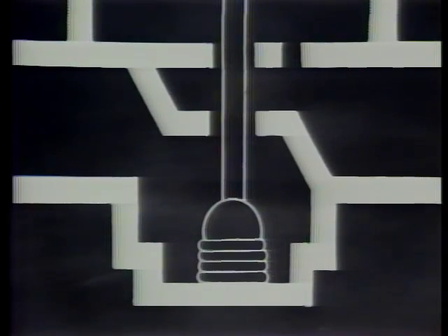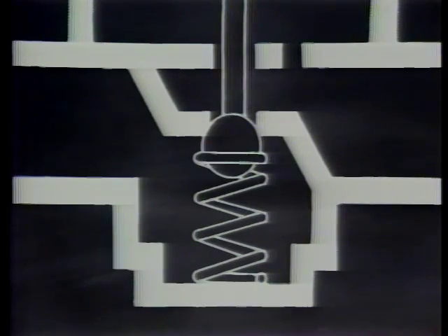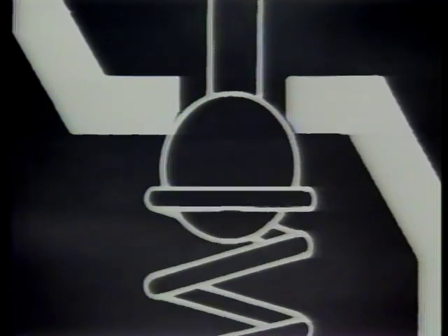If the valve opens in the direction of flow, the pressure works to open the valve, and these problems do not occur. However, only the force of the valve spring is available to close and seal the valve, so soft seats or soft valve plug inserts, which erode easily, must be used to ensure tight shutoff.